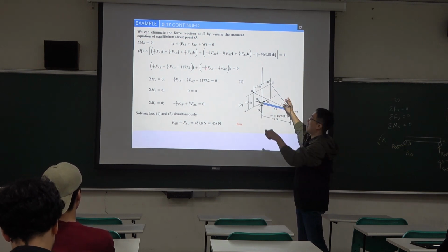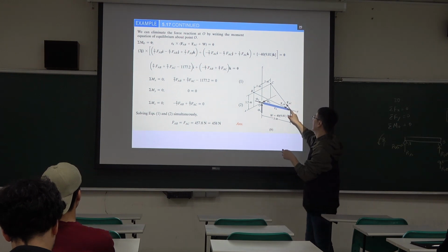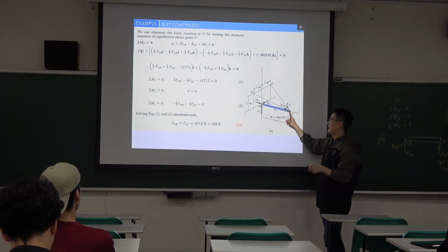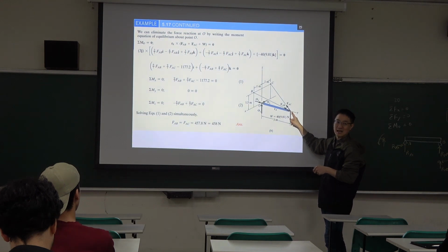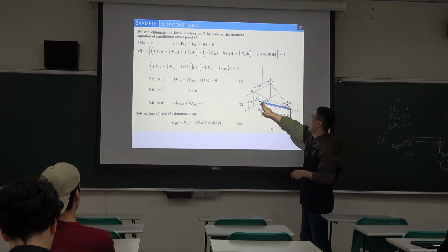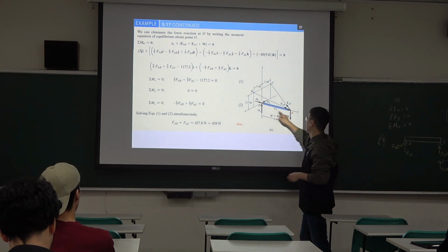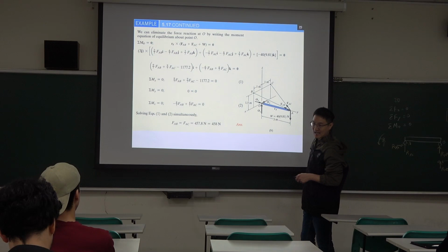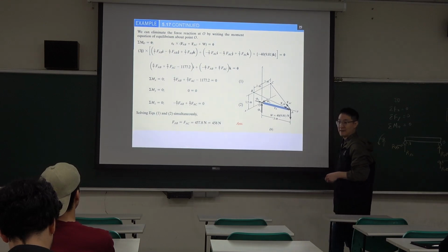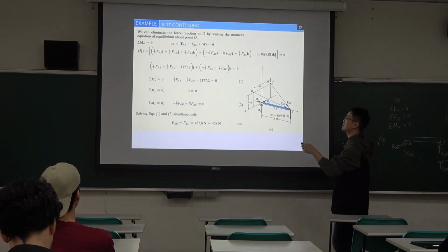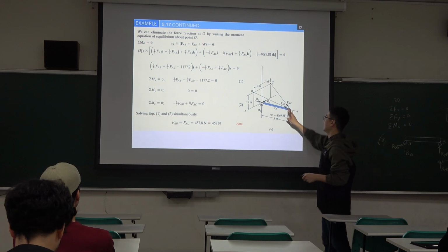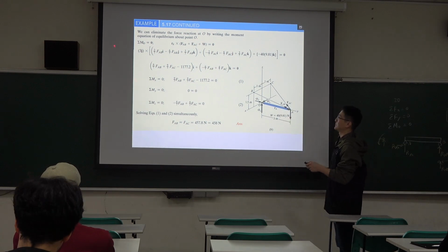But all forces intersect here. That's a concurrent situation; they all touch the same point. So we just use one position vector crossing these three forces together, and this position vector is RA. So use cross product and they should equal 0.